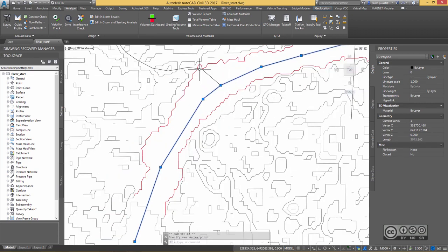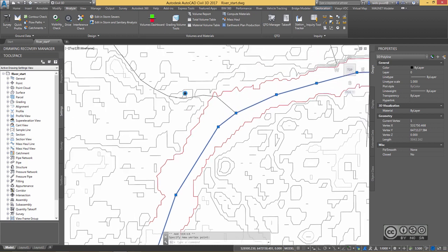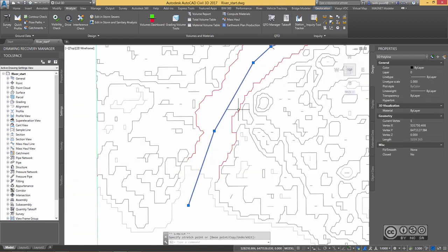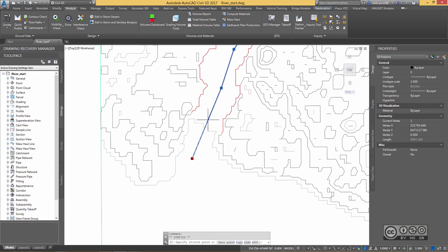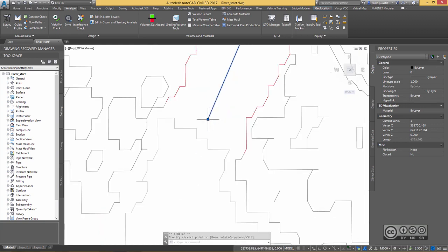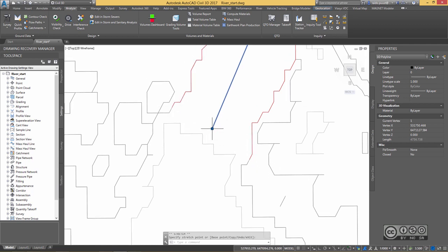Okay, in here we see two different rivers are connecting with each other, so another river is coming into this one. I maybe shift it a little bit up, also shifting this vertex, maybe adding one more here, and some changes close to shoreline. I want to ensure that my line endings are at about the same level, because we are creating cross sections based on the 90-degree rule.